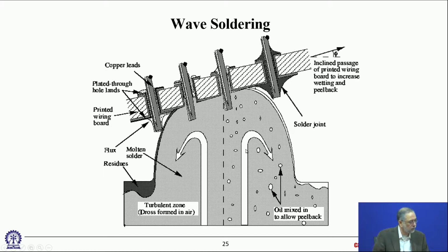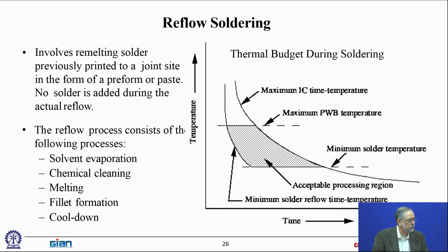Let's follow that train of thought we have been on for surface mount. So now I've placed the component. Now I have to go through the reflow process and melt the solder. There are two main parameters. Well, there are multiple concerns over here. The most important one is you have to stay above the melt temperature of the solder long enough for good intermetallic layer formation. Otherwise, you haven't formed a joint.